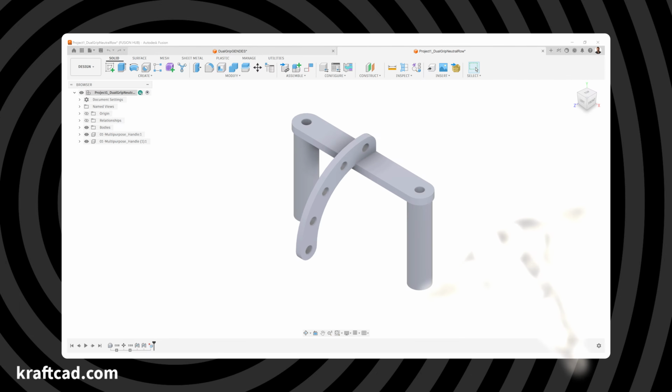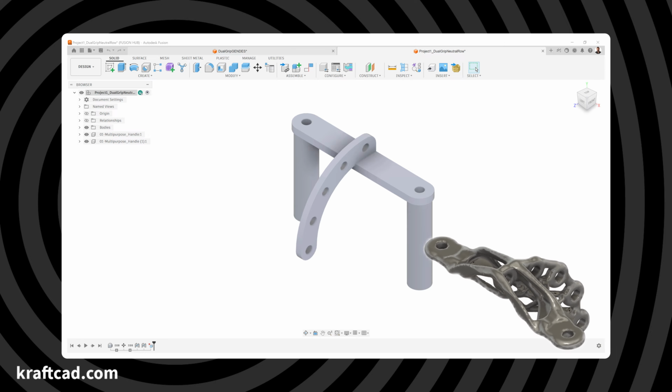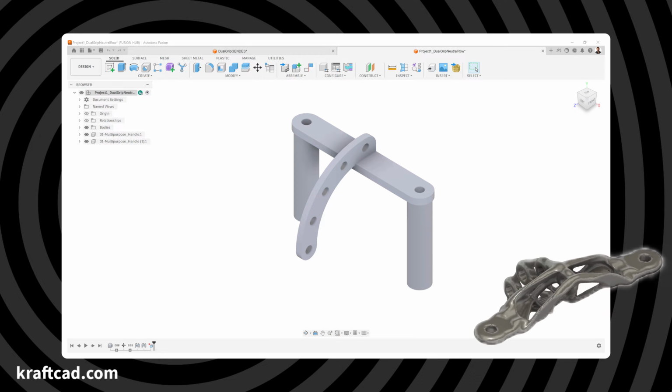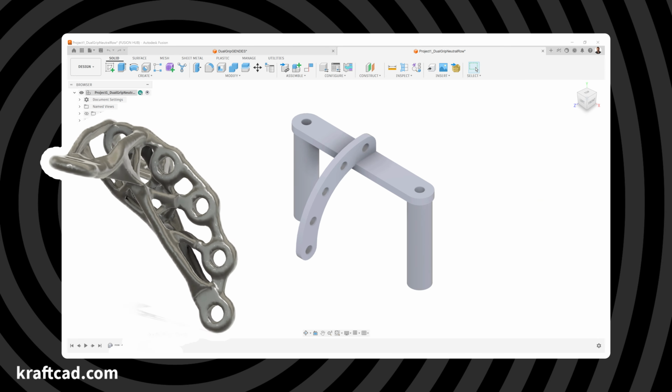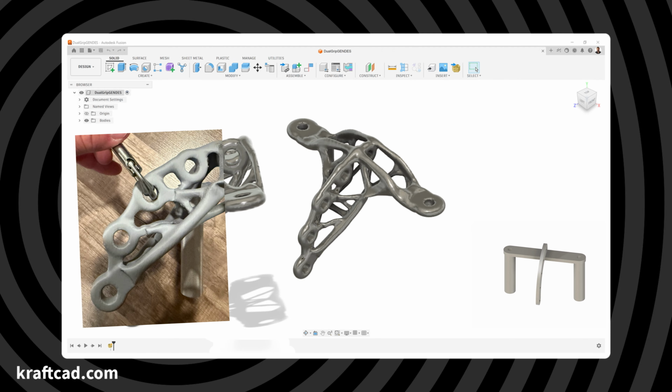The client supplied step files for the main attachment and the handles. These files defined the important dimensions and the way the product would be assembled. The handles would be machined separately and bolted onto the printed part. The 5 carabiner holes also had to keep their exact dimensions and positions because they allow the user to connect the cable at different angles.